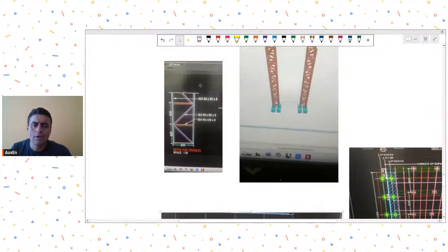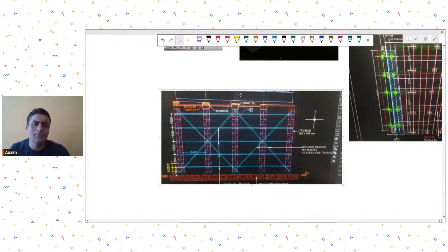Basically, some people make a full model, and some people just do quick manual calculations for it. If you want, you could also do a small full model. In my opinion, there is no need to model these trestles as four elements like this. You model them as line elements and take the property from the section wizard.